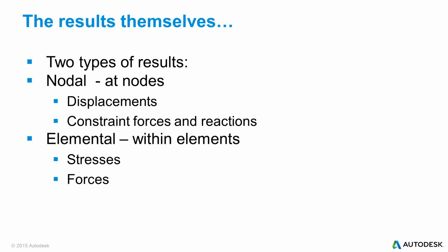Applied loads are always applied at the nodes. So those are formally what we call nodal results. The other results that come out are elemental, produced on an element-by-element basis: stresses, element forces, layer stresses, composite forces. Those are all elemental values.